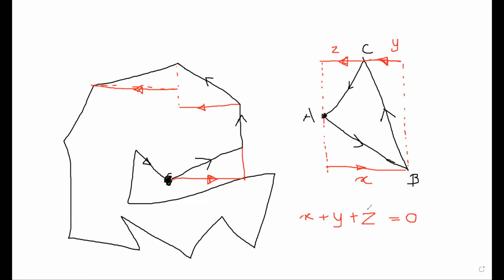So you have to go in the correct order. If I take CB, then it will not be 0. If I take CB direction, delta E of CB, it won't happen because then Y is a positive number, so then X plus Y plus Z is not 0. Because here we have marked all the lines in an order. In your travel sheet, you start with AB, BC, CD, likewise, come back to A. Then the summation should be 0.